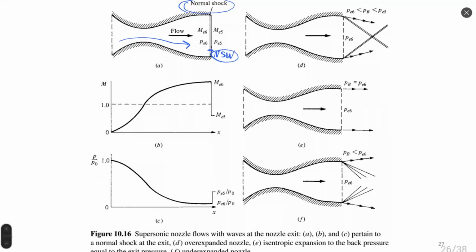You remember probably that in normal shock wave theory, we have analytically defined the pressure ratio as a function of Mach number. So depending on your Mach number on the exit of the nozzle, which is a function of area, you can calculate the pressure ratio. And it will also be a function of area because Mach number is a function of area, which simplifies a lot. I gave this example in one of my videos, and Anderson is also explaining how to calculate such a case.